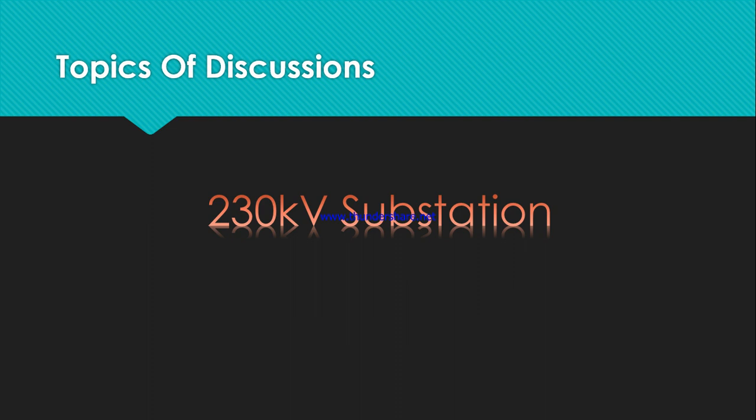Then we'll understand the 230 kV substation. It's a gas insulated system. This is a modular type of substation. It was supplied by Areva, France, and the control and supervisory system is connected through the open gateway as per IEC 61850 protocol, I think.